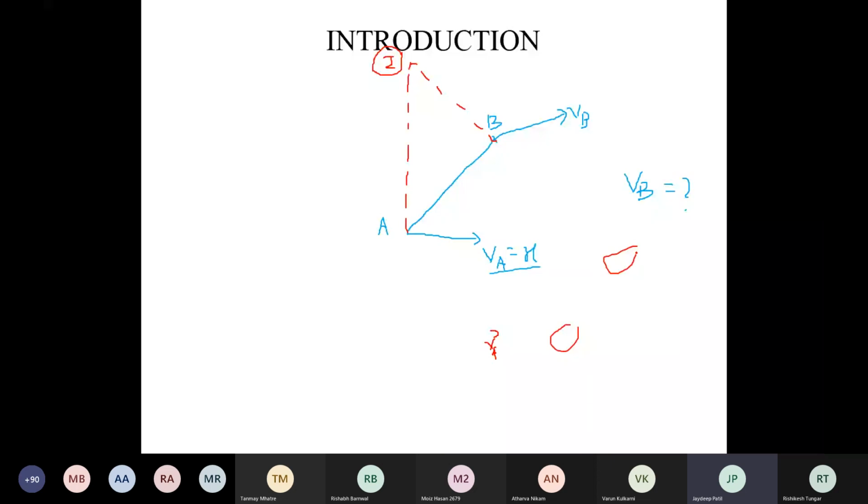In this case, we don't know the new position of AB. You have to draw the perpendicular to the velocity of A and the perpendicular to the velocity of B. Where they intersect, you will get the ICR. It means your link AB will move as if rotating about this point, like this. Now this is the center of rotation of AB.